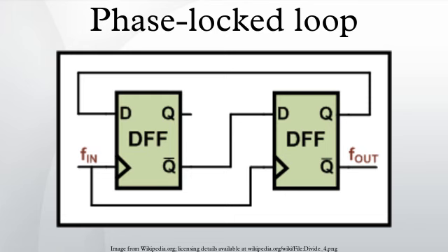It should also be noted that the feedback is not limited to a frequency divider. This element can be other elements such as a frequency multiplier, or a mixer. The multiplier will make the VCO output a submultiple of the reference frequency. A mixer can translate the VCO frequency by a fixed offset. It may also be a combination of these, an example being a divider following a mixer. This allows the divider to operate at a much lower frequency than the VCO without a loss in loop gain.